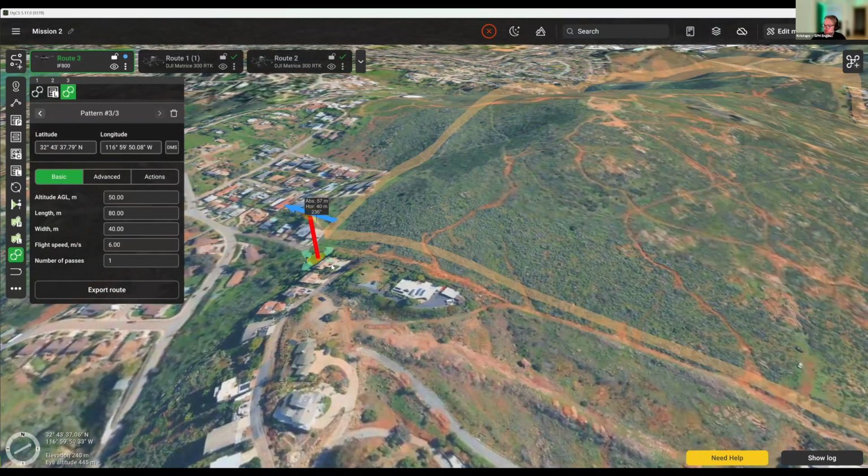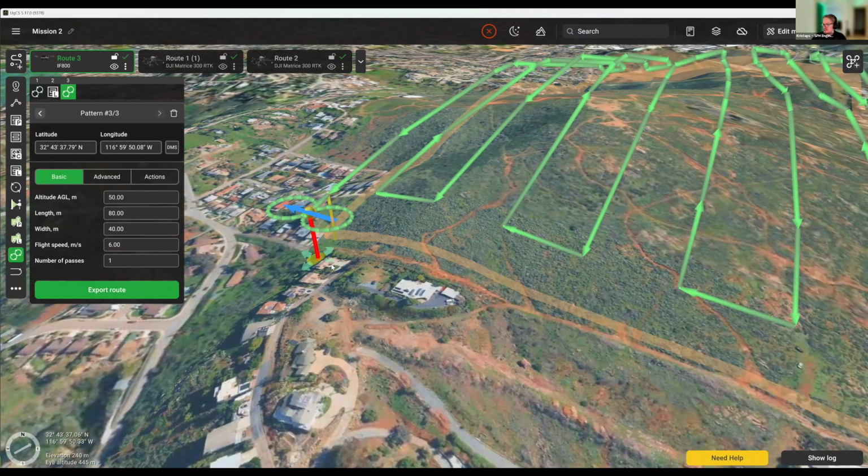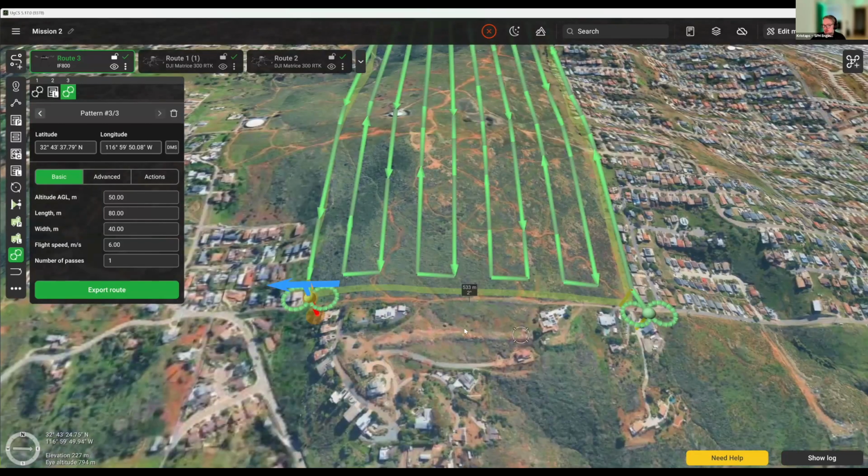This will depend slightly on which IMU, on which LiDAR you're using. For some, it's required to do this both at the beginning and at the end. I would say that's the most common one. But for some, I've heard that it's also okay to just do it at the very beginning and there's no need to do it at the end. But I think usually the case is both at the beginning and the end, you need to do the calibration. And so this is how it looks like.